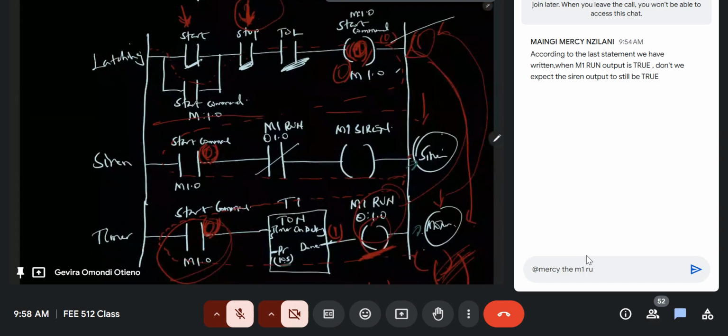Remember, I told you that the scan cycle happens so fast, in milliseconds. So what needs to happen is it runs through the entire set of your ladder diagram and reads the state of each of the contacts and the outputs. Then it executes instructions as indicated by each of the inputs. And then remember, it has even read the states of the outputs in the first instance. So the first instance is simply read.